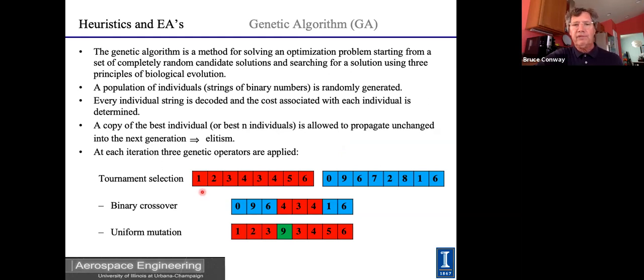So for example, the first 3 numbers here could be the departure date following some given epoch date. The next 2 could be, let's say, the time that the astronauts are on the surface of the object, asteroid, or maybe even Mars. And then these 3 numbers could represent the number of days after the stay that you arrive back on Earth. So that information is sufficient to solve the Lambert's problems to give you a delta V cost for the mission.